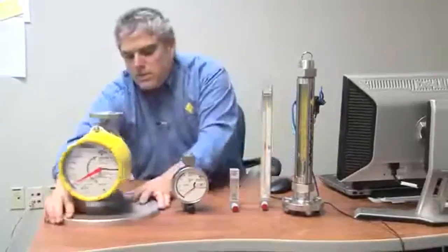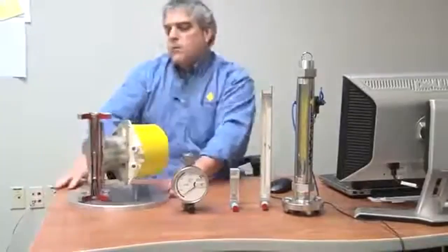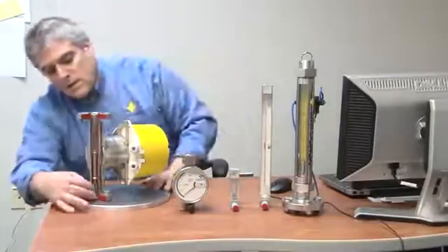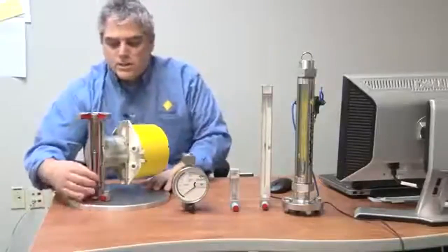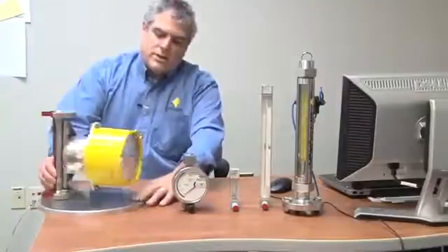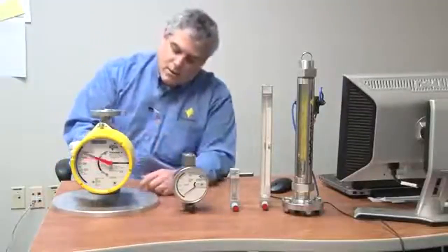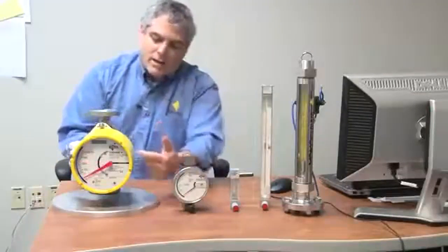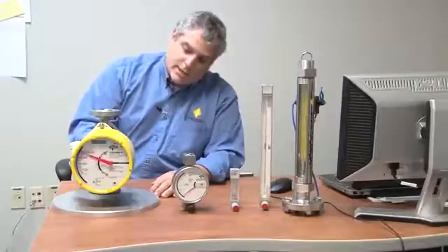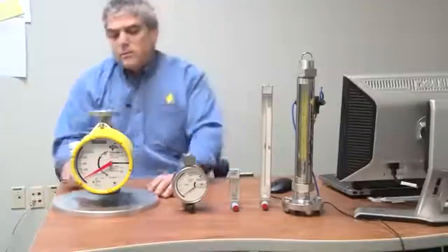As I said, it's a variable area meter. If you turn this to the back side, you have a rotometer actually connected to this. So there will be deflection. What we have done is the opening is done such that you can see the float material moving up and down. As it is moving up and down, you can see there is deflection in the calibrated scale. It's like a speedometer we see in our car or two-wheeler. So when the float position is changing, we have change in the volumetric flow rate, which we can readily read through the calibrated scale attached to it.